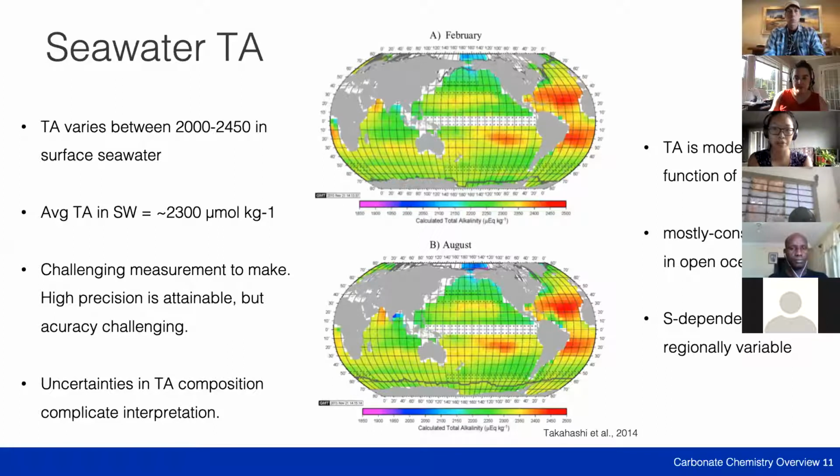Yeah, if you want to make an alkalinity salinity relationship, you're going to need to have samples for both of those things that cover seasonal changes. So if you live by a river or something like that that will change the salinity, then you need to cover when that river is going to be higher volume, putting fresh water into your region of study. But yeah, we can go into that. I'll be done with this part soon, and we can go into more monitoring aspects.